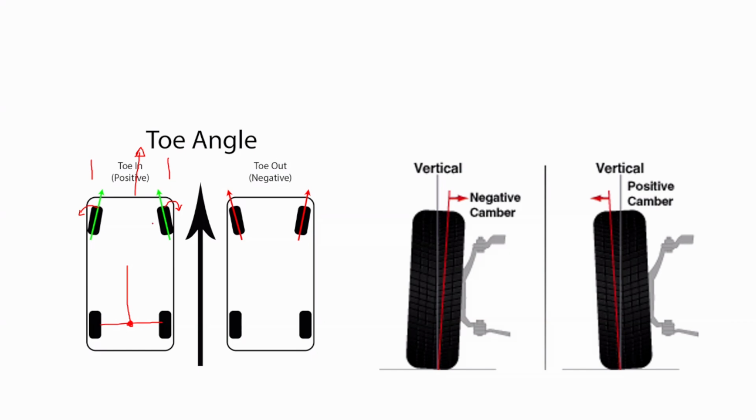Let's assume it's zero, but it depends on the vehicle speed and the given torque. But anyway, if our vehicle is a rear wheel drive vehicle, the toe angle should be positive. Once we start driving, the toe angle will be reduced. It will be almost zero, right? So that is why positive toe angles are recommended for rear wheel drive vehicles, right?